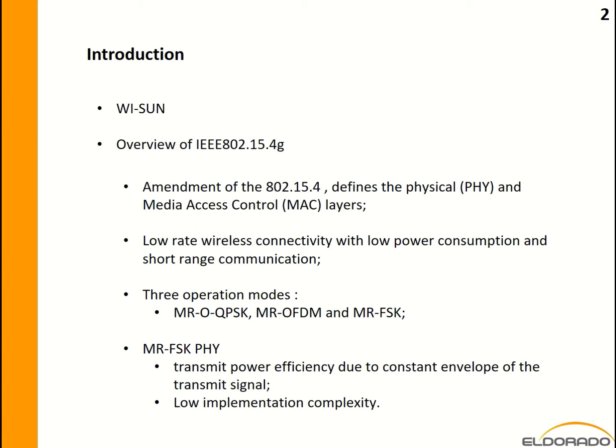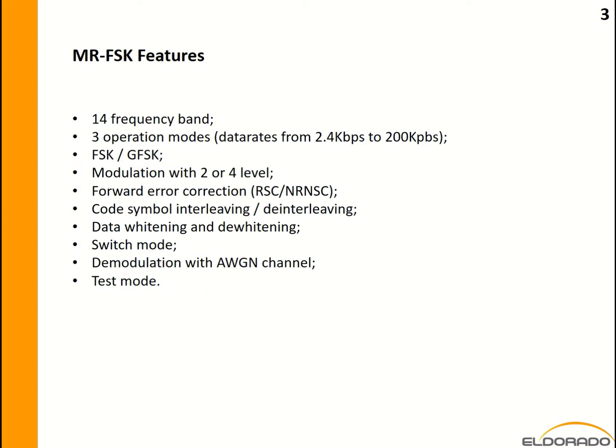Every PHY in the standard tackles three operation modes: the MR-O-QPSK, the MR-OFDM, and the MR-FSK. This work focuses on the functional verification of an integrated circuit MR-FSK PHY. Some advantages of the MR-FSK PHY: transmit power efficiency due to the constant envelope of the transmit signal, and low implementation complexity.